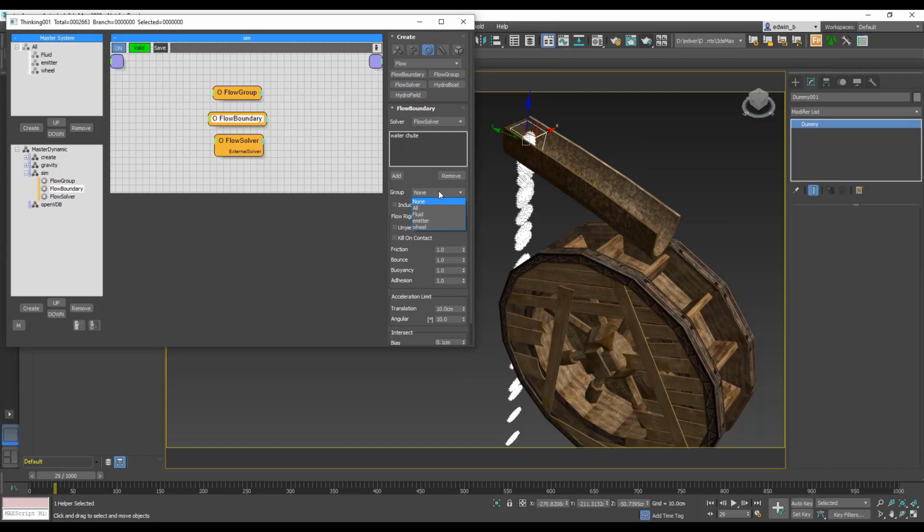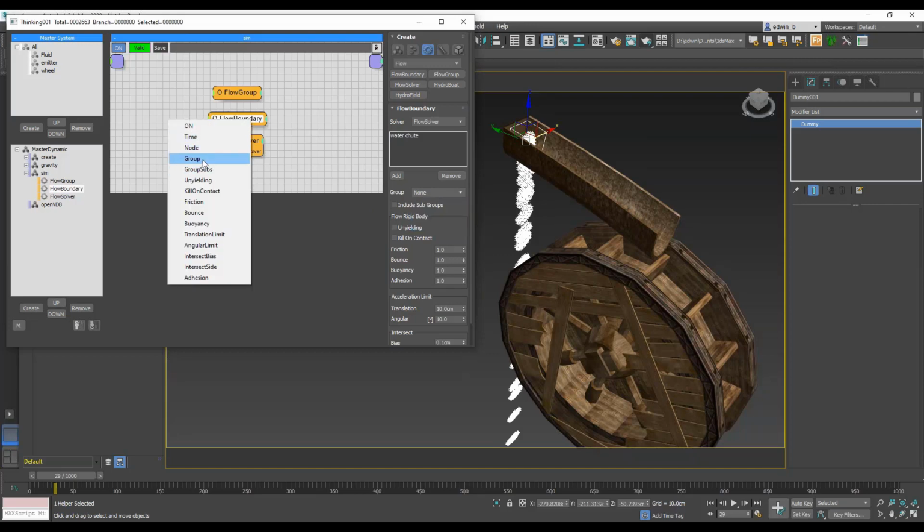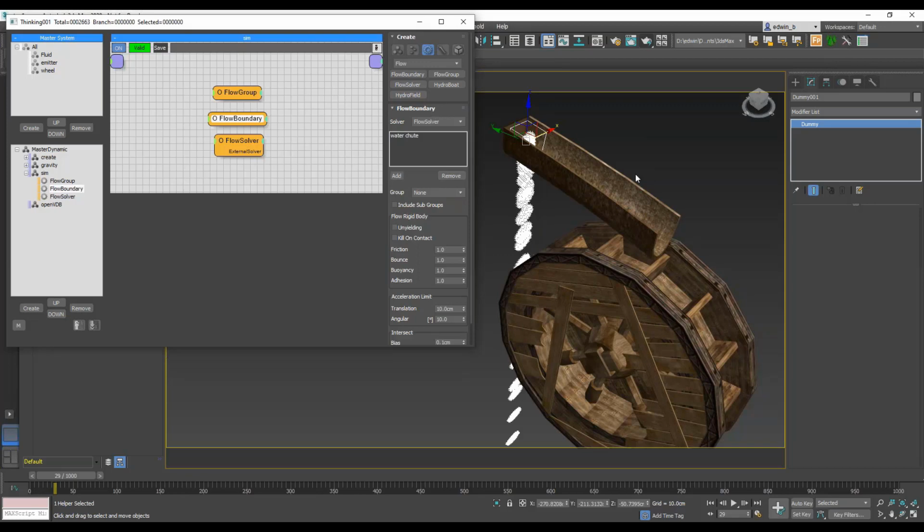So we could have brought in the pipe as a particle and then feed in the group of particles, or choose the particle group here. So that's also possible. But as I said, I'm lazy, so I like to pick just the pipe here, and that's it. The next thing I want is that it's unyielding, so this thing shouldn't move. The particles should bounce off and flow down.